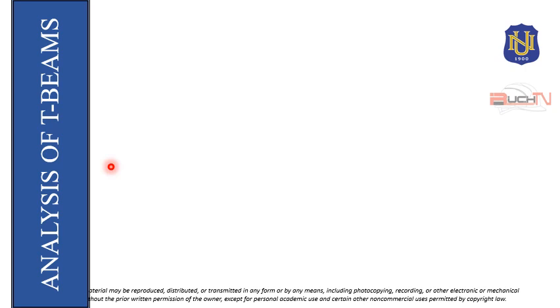So, of course, we can now proceed on the analysis of the T-beam itself. What if we proved that our a, the depth of the concrete compression area, is greater than the thickness of the slab, or the flange? I will be introducing 3 methods to solve this condition.